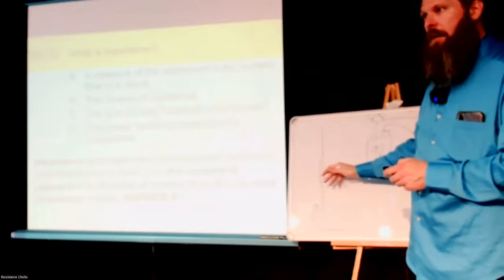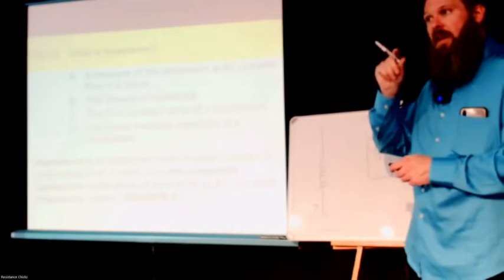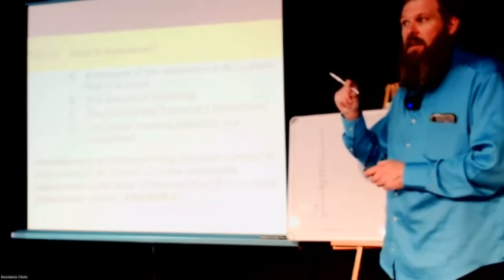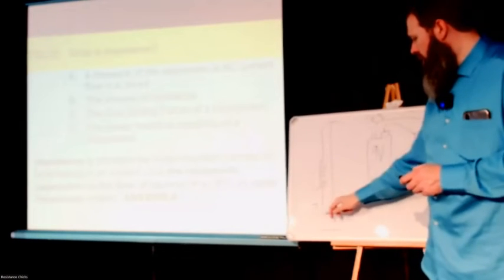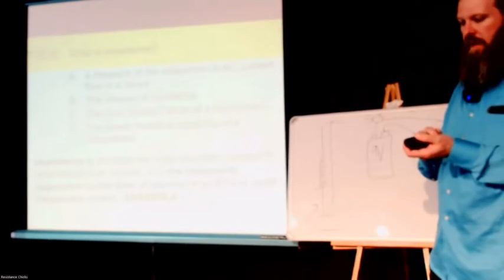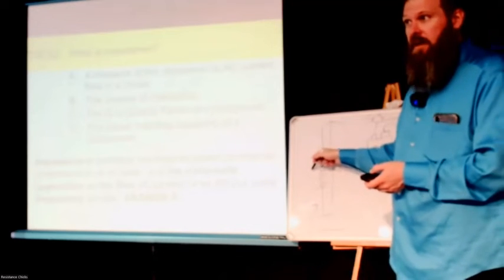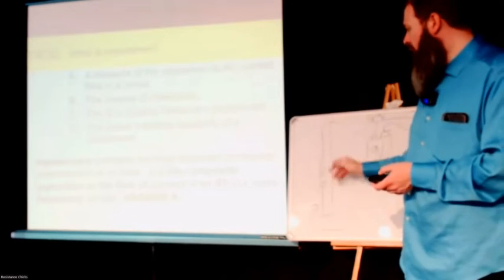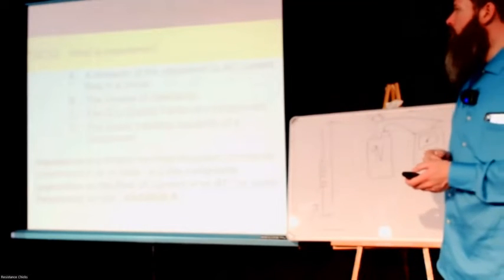And it hits it and stops and says, okay, well, I guess this is all the antenna that I'll use. But then when you send a different frequency of the signal, it just blows right through there and utilizes the whole thing. That's how that works, because this coil is an inductor and it's tuned specifically for what frequency you want it to oppose.